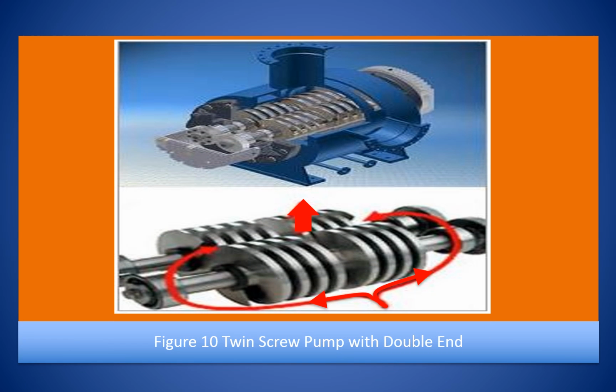The next widely used type of pump under the positive displacement rotary type is the screw pump. These find applications in several industries, in refineries and petrochemicals, particularly for viscous applications. Screw pumps are a more complicated type, featuring two or three screws with opposing thread. One screw turns clockwise, the other counterclockwise. The screws are mounted on shafts that run parallel to each other.